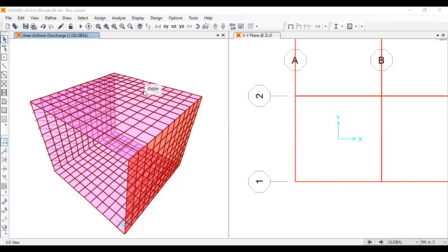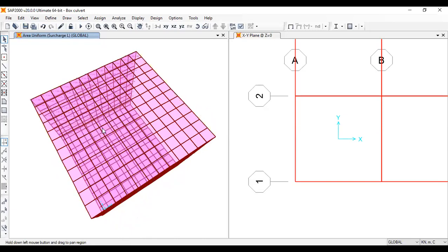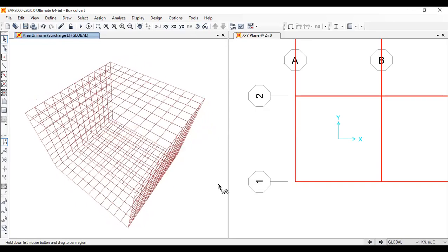So next thing is you need to apply the HB loading due to the vehicles. The critical location is when two wheels pass the center line. The y direction is the road direction, so perpendicular to that, you will have the axles.